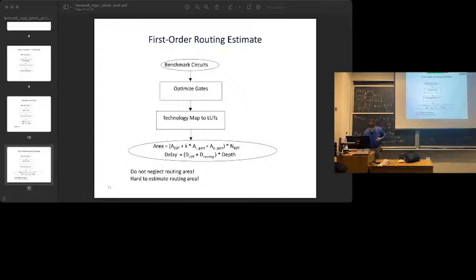Same thing for the delay of the routing. So I put some number in for the delay of the routing. If I'm changing the lookup table size, for example, am I going to assume that the delay of the routing is constant? Am I going to assume it's changing somehow because maybe things are getting spread out or wires are getting physically longer? I don't know, right? Without doing a whole bunch more modeling, I just don't quite know what to put in there. So it's better, but I'm going to have some difficulty justifying these, because I'm going to have to do a lot of guessing.